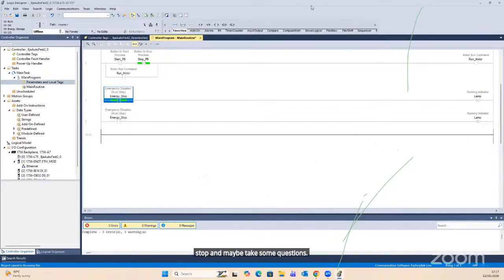So outside of your Boolean and regular data types, you have other data types you can use. Say you want to create an alarm. These are other bit instructions as well: one shot rising and one shot falling. One shot rising is your rising edge or positive edge. Did we touch on that in Siemens? We didn't touch on that in Siemens.